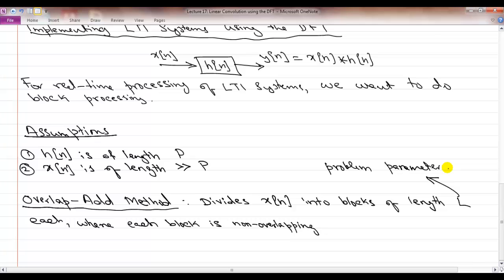the output. On the other hand, if L is too small, if L is like 1, then you don't really have any advantage as far as using DFT goes. Right? So you really want to pick the L in the right fashion so that you obtain the speed up of DFT or FFT effectively.